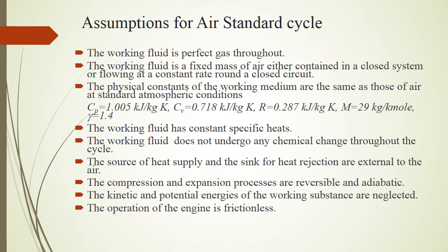So with these assumptions, the work output, the maximum pressure, maximum temperature of the cycle, and thermal efficiency based on the ideal air standard cycle are obtained with higher values than those of the actual engine.